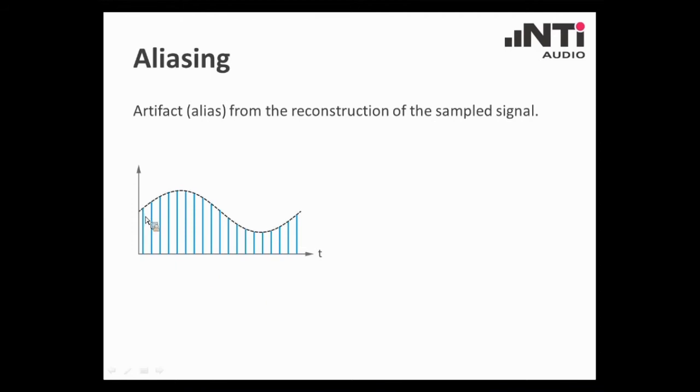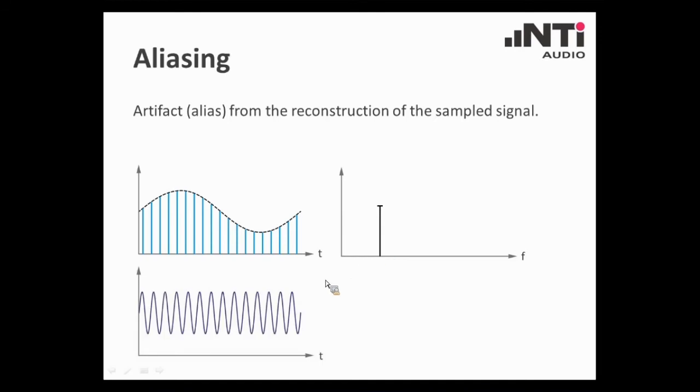And that is happening quite exactly here with this high number of samples for the sine wave. And based on this data, based on this reconstruction, the analyzer can calculate the corresponding bin of this sine wave. However, what happens when we have an input signal with a much higher frequency? The analyzer would do the same. It would sample this signal with the same sampling rate. You can see that here.